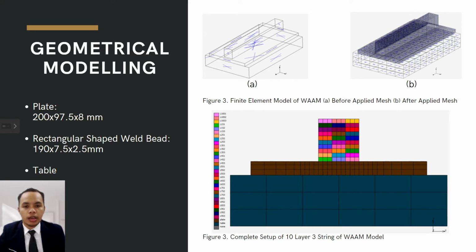As a solution, an extra stable element was added to simulate the removal of the support and base plate from the end component of the model. Since the geometric form of the workpiece is relatively uncomplicated, quad meshing was selected as the kind of meshing to be used. A simpler mesh is used in order to reduce computation time and make the modeling process easier, since there will be less strain and change in form.